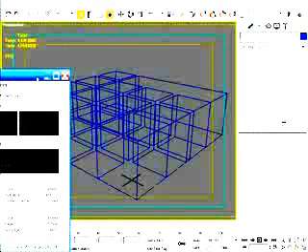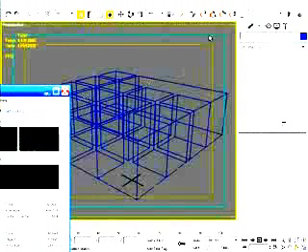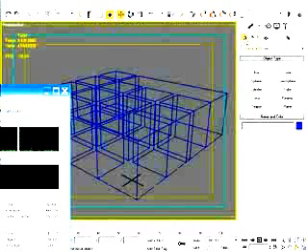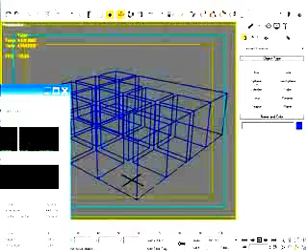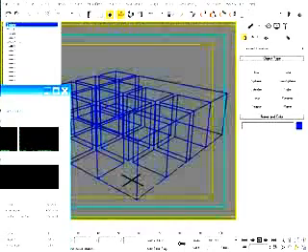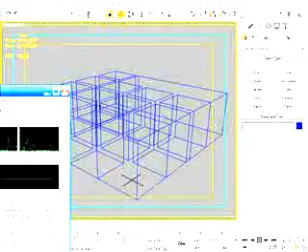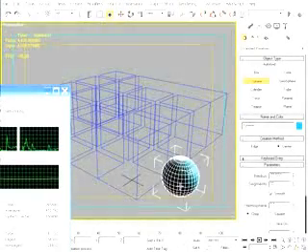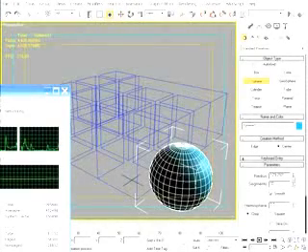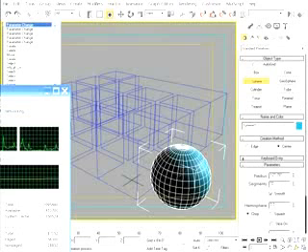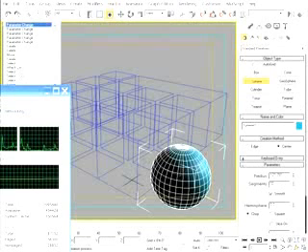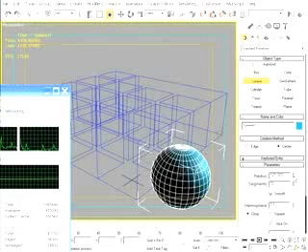So instead, all I need to do is create an object and change a parameter or two several times until that one memory-hungry heavy attach command is purged from the undo list. So I'll create a sphere and change the radius several times, and as I change it, notice in the undo drop-down list the Convert to Editable Mesh step keeps getting pushed farther down in the list.